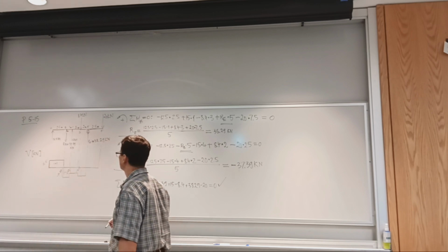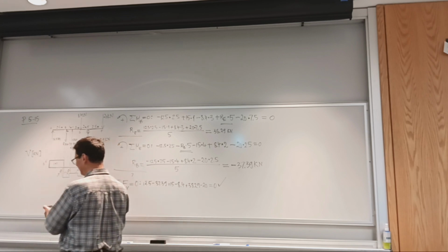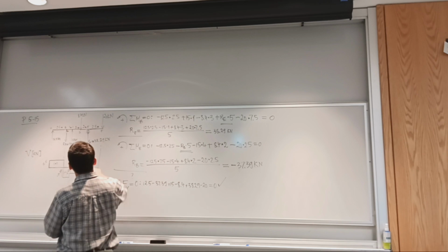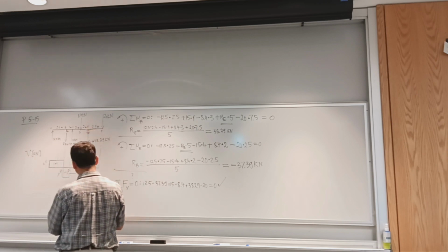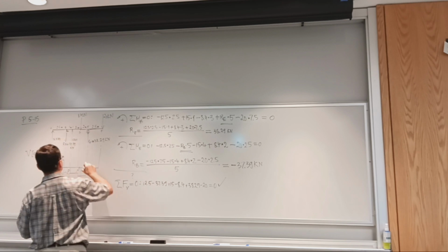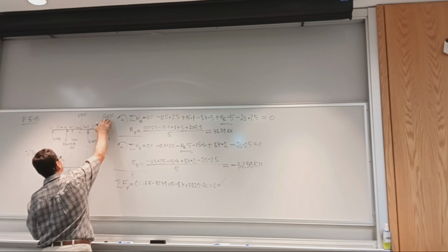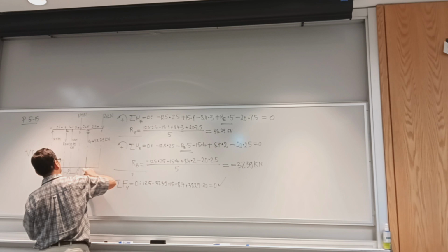And then I have an upward jump by 38.29. I'm at negative 18.29, and I run into the reaction at E, which is positive up, so I said plus 38.29. And this is positive 20, which is encouraging because we'll close the diagram with the last external force.